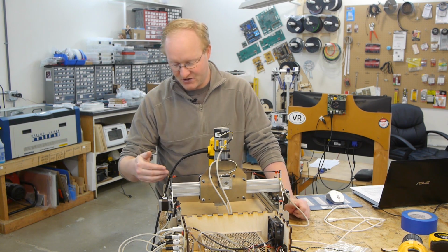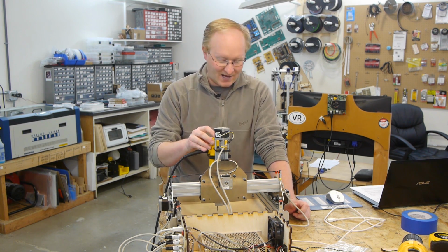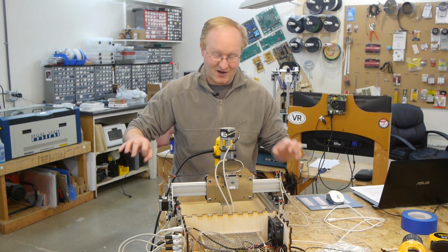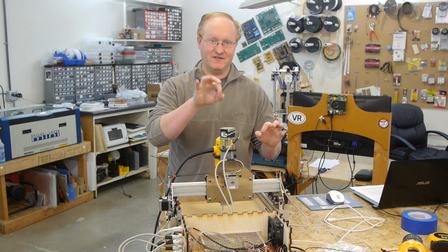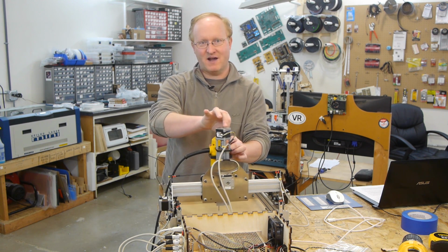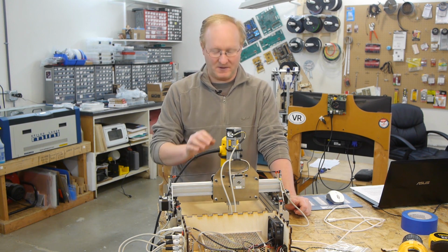There are also machines where the belt will loop at the end, although you won't have as much torque with that. You'll also see machines that have threaded rod. It'll be basically a long threaded rod, and there'll be a captive nut on that. And when the rod rotates, the nut will move the entire system back and forth. You get a lot more torque with something like that, but the speeds are a lot lower.